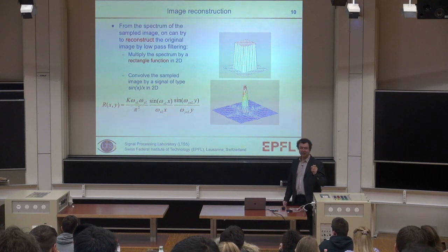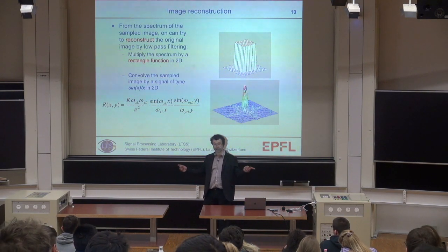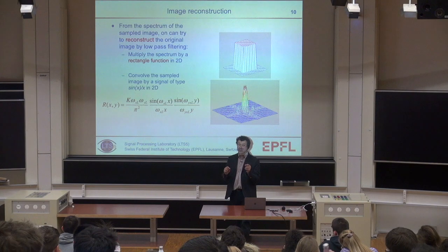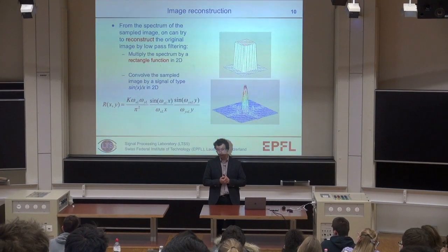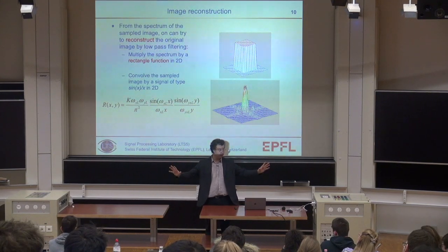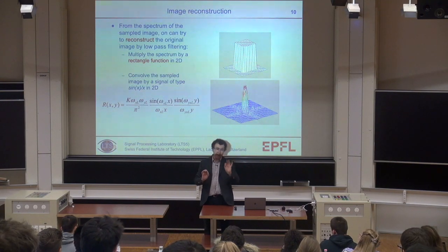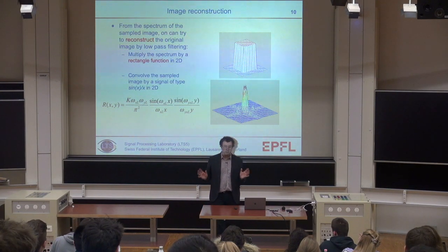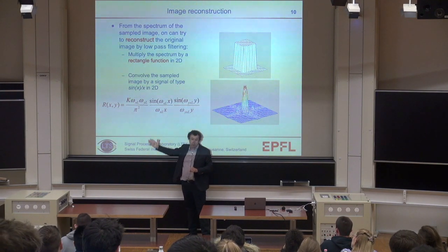Anyway, obviously we don't do interpolation by a sinc, by a real sinc, because it's infinite support. So when you do image reconstruction like that, if you want to interpolate correctly, you do the best approximation you can of a sinc. Because what we are doing here is really interpolation, right? You have your original pixels that are the sampled version of your reality, and doing an image interpolation means that you want to find the value between the pixels, and if you are good, you want to find the good value of those pixels. So in an ideal world, you would do this interpolation using that kernel. In practice, you do a little bit less.